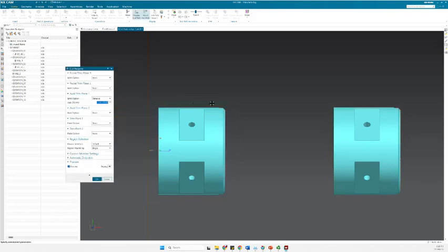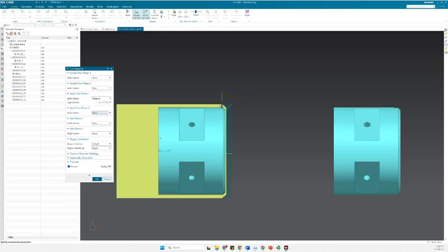So it's clearer now, the cutting path. We have both facing and the outside diameter, and this is something we would like to avoid, having it only with the face of the part. One way to do that is to move this axial plane that now is -5, for example, to the number that goes ahead of this. So let's move it to 32.